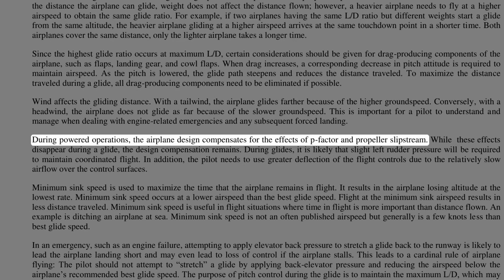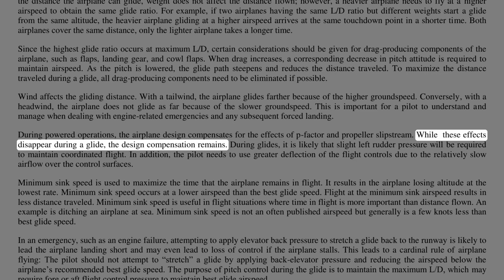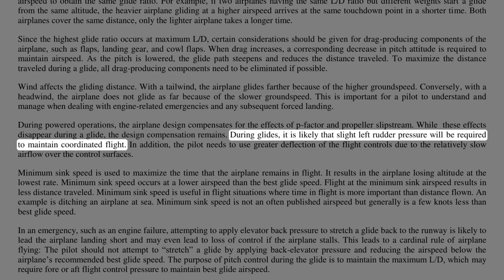During powered operations, the airplane design compensates for the effects of P-factor and propeller slipstream. While these effects disappear during a glide, the design compensation remains. During glides, it is likely that slight left rudder pressure will be required to maintain coordinated flight.